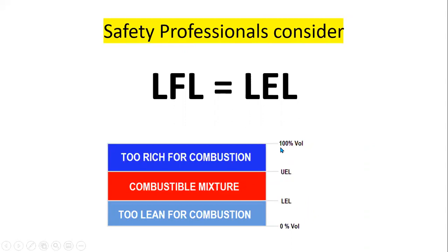It will not explode. Now, I wouldn't take a lot of comfort in that, because if it's above that and you go in and start ventilating, you're going to drive it down to this area and have an explosion. So the key thing is this, the lower explosive limit. That's what we really want to work on, and we want to monitor for sure.